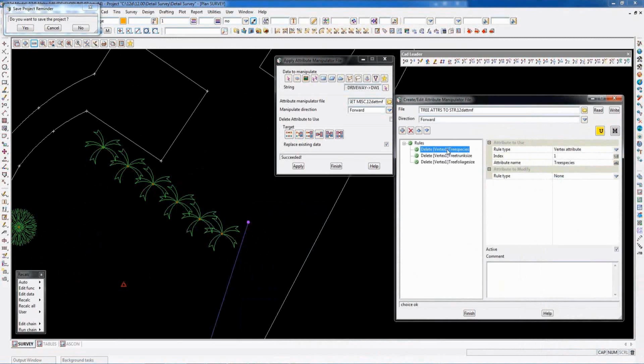We're going to set. So drop down the first one. So we're going to use that. So what do we want? We want that to be a string attribute. And it's going to be called the same name. That makes sense. And we'll just let it go auto. Drop down to the next one. Again, that's also going to be a string attribute. It's a trunk size. So I want to also have that as the same attribute name.